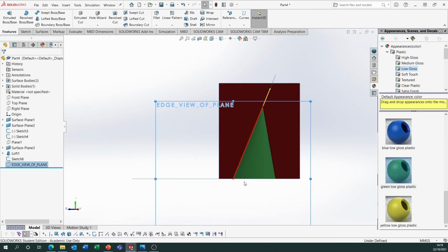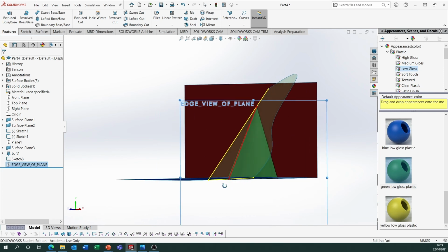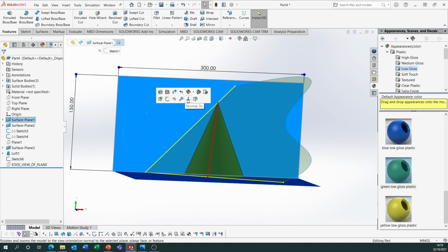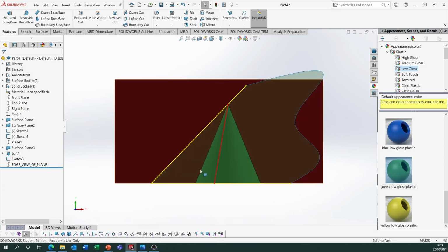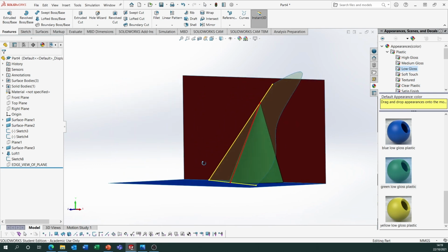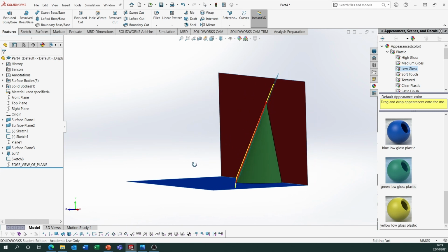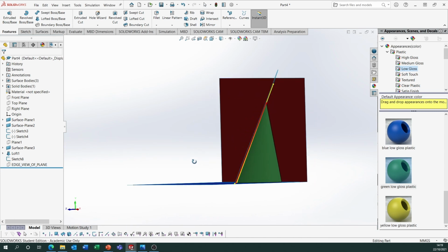So that angle on the cone stays the same the whole way around the cone. Then when we look in our elevation, the angle of the cone there gives us the true angle of inclination between the horizontal plane and the oblique plane, because that angle stays the same no matter how I revolve it around, and the cone itself is a tangent to the oblique plane.